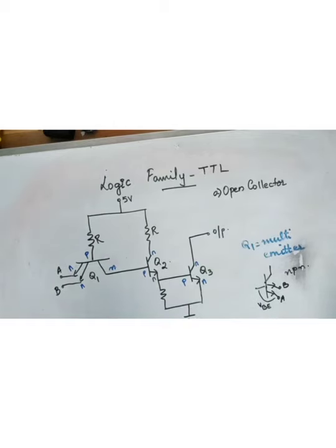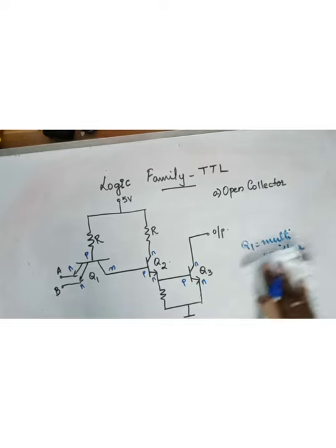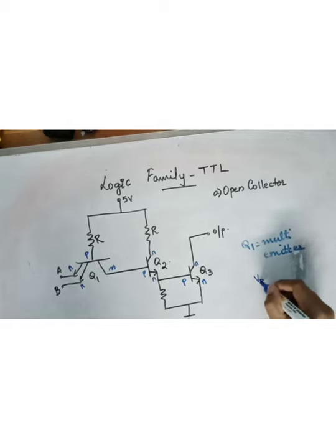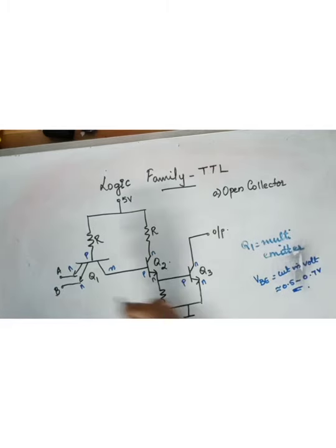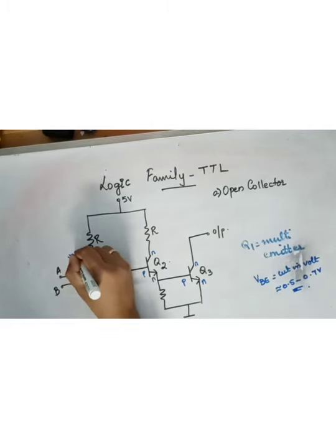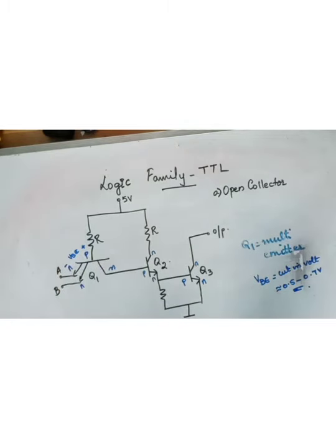So we know that for an NPN transistor, the transistor is on when the base emitter voltage is at least 0.5 volt. That is, base emitter voltage should be equal to or greater than the cut-in voltage. That is approximately 0.5 volt, 0.5 to 0.7 volt it will be. So the base emitter voltage should be around this voltage. Then this particular transistor will be on.